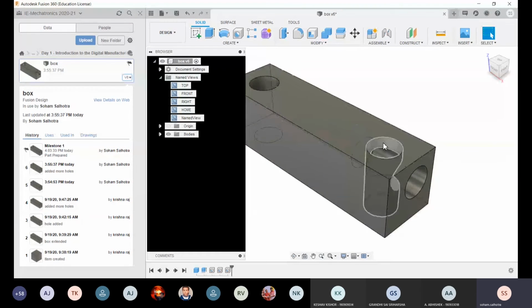So now we have extended the design's length by 10 millimeters without affecting any of the forthcoming features, which is often a problem in other software such as SolidWorks and CATIA, because just changing one dimension can break the entire flow and you need to redefine all your constraints.